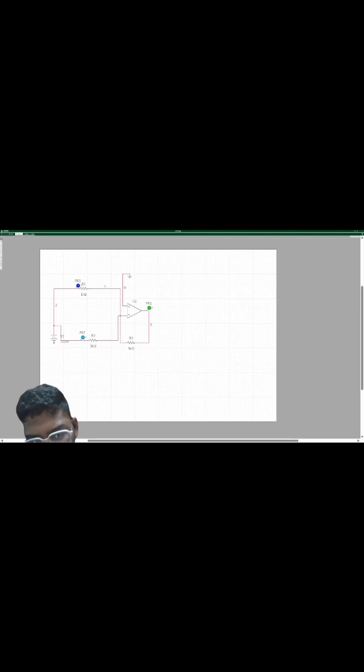In the off state, no base current is present. The transistor remains in cutoff and the LED is off. When the switch is pressed, the base-emitter junction receives sufficient voltage to turn the transistor on, allowing current to flow from the collector to the emitter, lighting the LED.